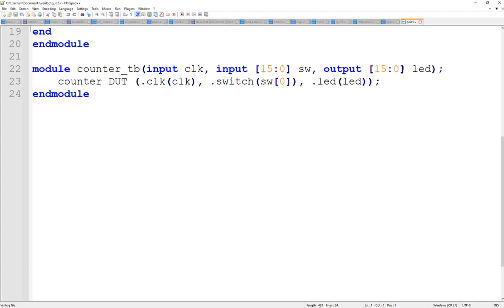A lot of times you program in the exact way we have been doing, and eventually you are still seeing errors. If you have a lot of experience, you should know that if you couldn't find any big issues, the problems could be really tiny or minor, hiding somewhere else. Most recently, I was 100% sure the code was right. I was looking at everything, and it was still not going through. I eventually found out I declared the switch as the output. All the little tiny things hide somewhere. Just be patient and trust yourself whenever you are debugging your code. You know it's right. It must be something minor hiding somewhere, okay?